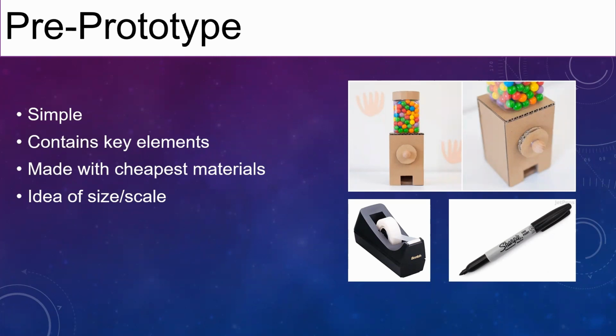Start thinking about how you're going to join the different surfaces together. One of the big mistakes where people lose a lot of money is they say, here's the box I'm going to make, and they don't put the screw holes in the right place. And then when they try to thread screws into it, they're cracking their material. They have to go back and redo a bunch of work.